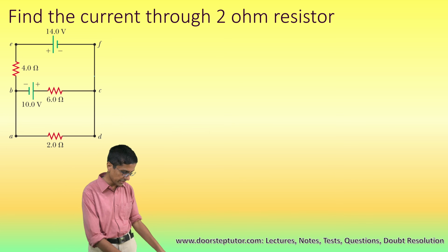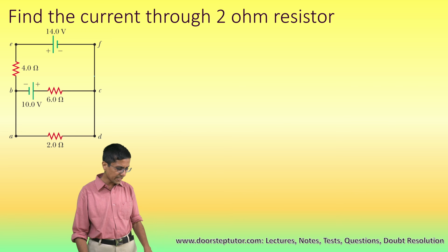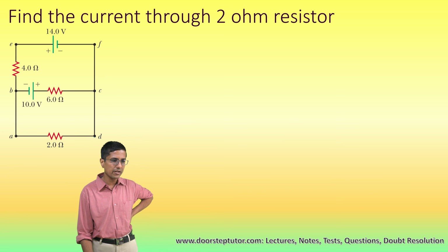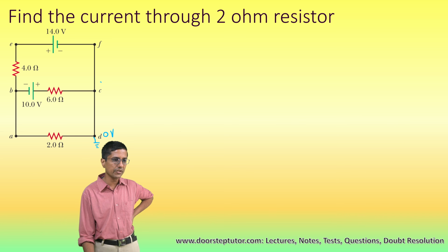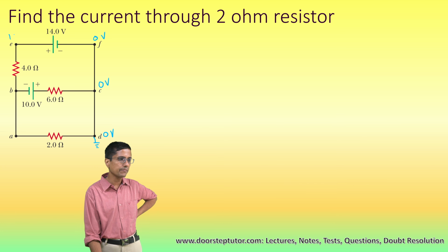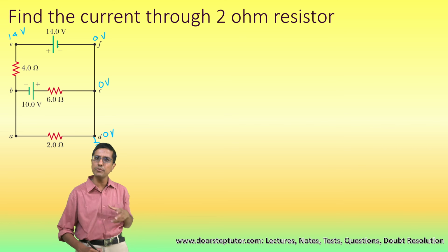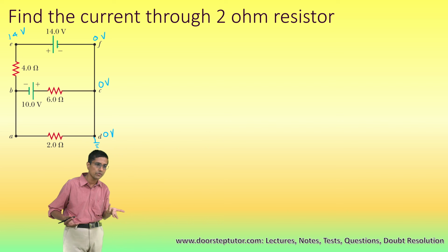I'll show that to you in a second. Now in this case, notice that we will again choose one of the terminals as a reference terminal, that is the starting point. So this becomes 0 volt, this becomes 0 volt, this becomes 0 volt, this becomes -2 plus, so this becomes 14 volt. Okay, here is 0 volt, I traverse the battery, so this has to be 14 volt. So E1 I also know.